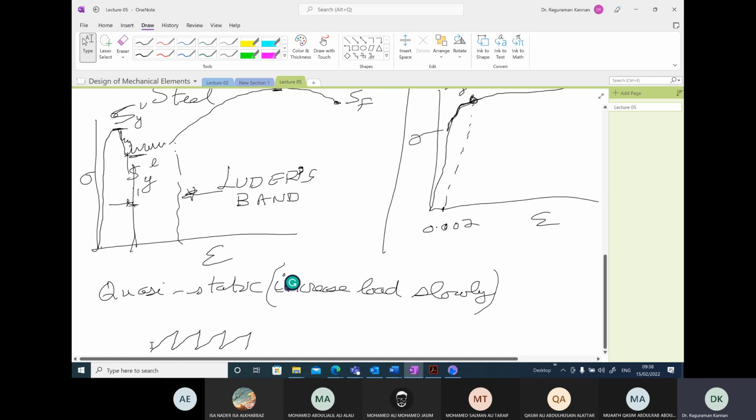First, when it increases, the local dislocations are not moving. Then suddenly the dislocations move locally, in some places, and then it decreases. Then more dislocations are created and they do not move. So now it increases. Again it decreases because now the dislocations are moving.